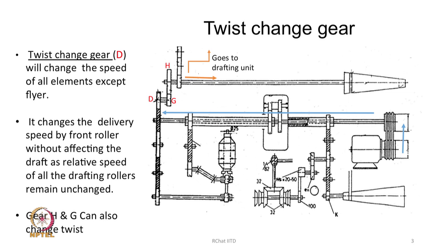So, the motor is here, from here it goes on the motor pulley to the machine pulley, and this particular shaft which is running across the full length of the machine is on the other end of this shaft. There is a wheel here, and then there is another set of gear D and G, a compound gear DG.